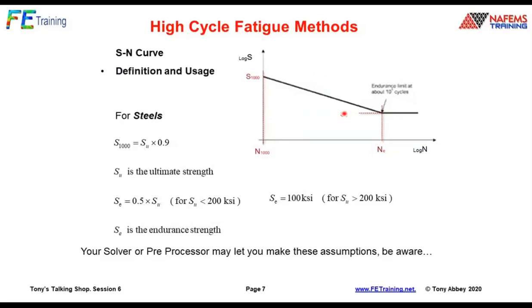If we haven't got that data, what we can do is take a bit of a flyer. We can take ultimate stress, which is above yield. Typically, some say 1.4 to 1.6 times yield. Say take 0.9 of that, and that's given us our point there, bang. Well, that's already laid some suspicion in our mind, in the sense of, well, I thought you said there has to be an elastic limit in there. So there we go, and bang, straight through that.